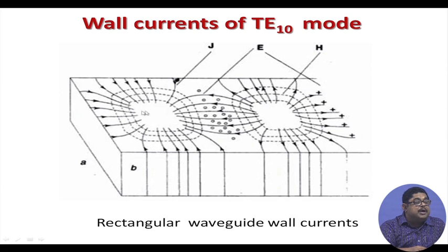Another beautiful thing is, if I do it at the center, we have already seen that in this cross section the electric field is maximum. So, when I am cutting the slot, I am not disturbing the magnetic field here, and obviously electric field cannot be here because this is a TE mode. So, no longitudinal electric field, but here at the center the electric field is maximum. So, in all the cross sections the central field is the maximum electric field. So, the beauty is when I am sensing, I can sense with maximum sensitivity, because electric field is maximum there.